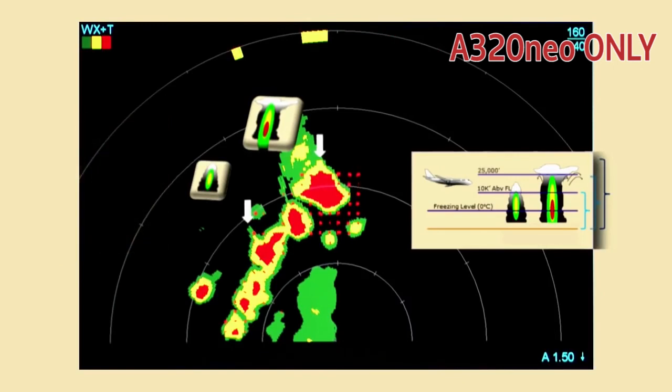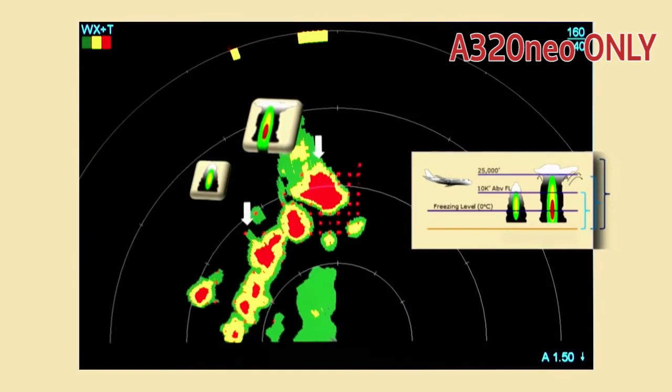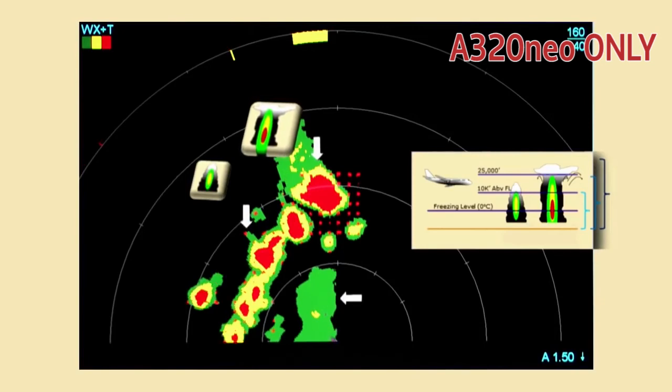Finally, above 25,000 feet, MultiScan ThreatTrack displays an anvil-top associated threat. The radar uses cruise-level winds to extend the threat region downwind of the cell. An example of this will be shown shortly. Note the more benign non-electrified cell directly in front of the aircraft. In this case, no associated threat icon is displayed.